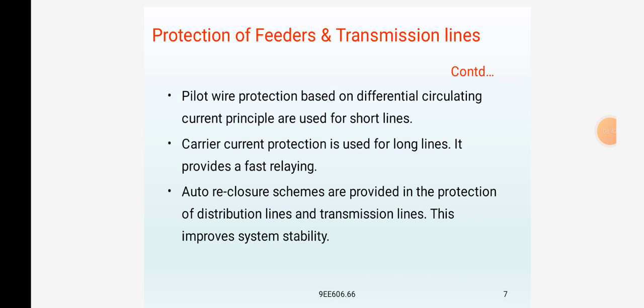A simple differential protection of a bus section: the bus bar is fed by a generator and supplies load to three lines. The CTs are connected in each circuit connected to the bus bar. The secondaries of these CTs are connected in parallel. The protective relay is connected across this parallel connection. All CTs must be of the same ratio in the scheme, regardless of capacities of various circuits.